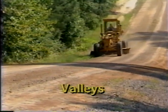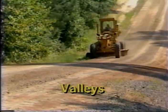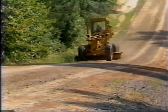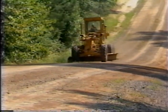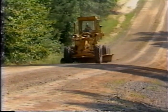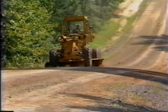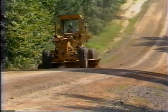Valleys or low points of vertical curves also create a special condition. Lower the blade somewhat in the low point of the valley to follow the profile of the road. Then gradually raise the blade as the grader moves on to the uphill grade.